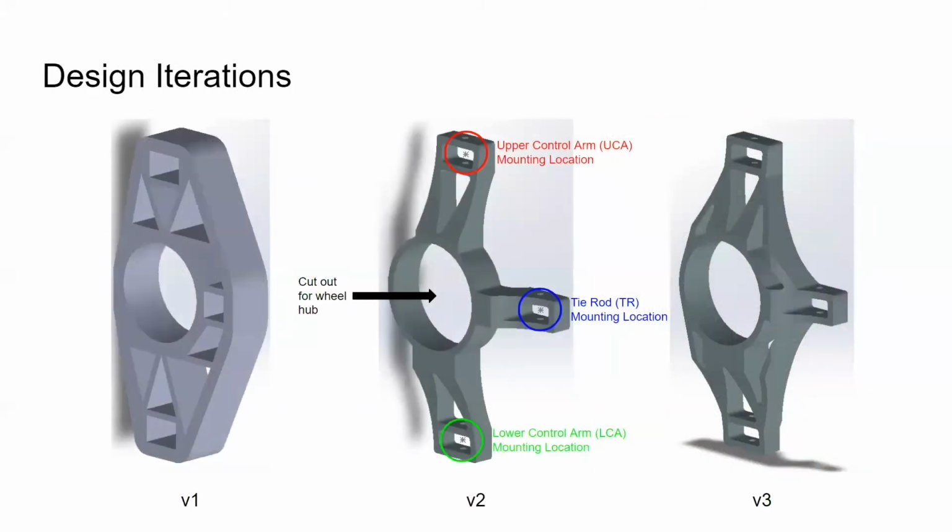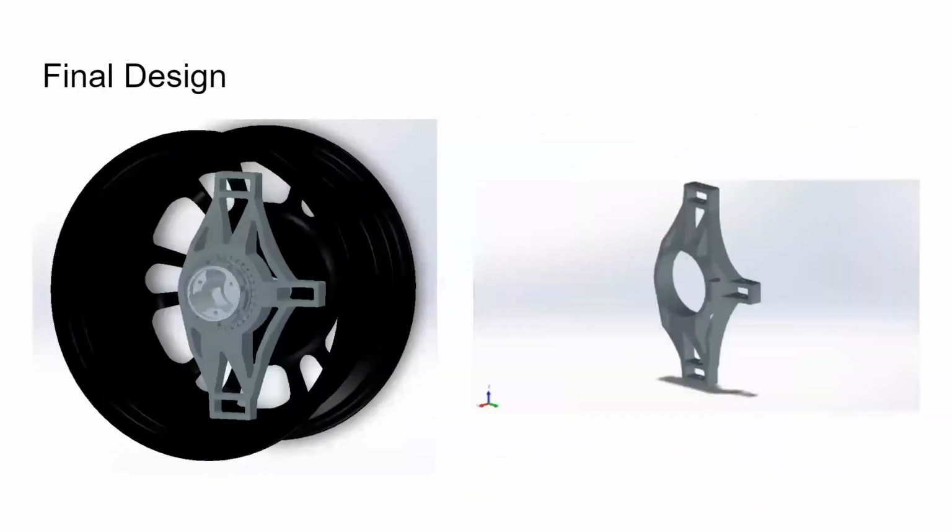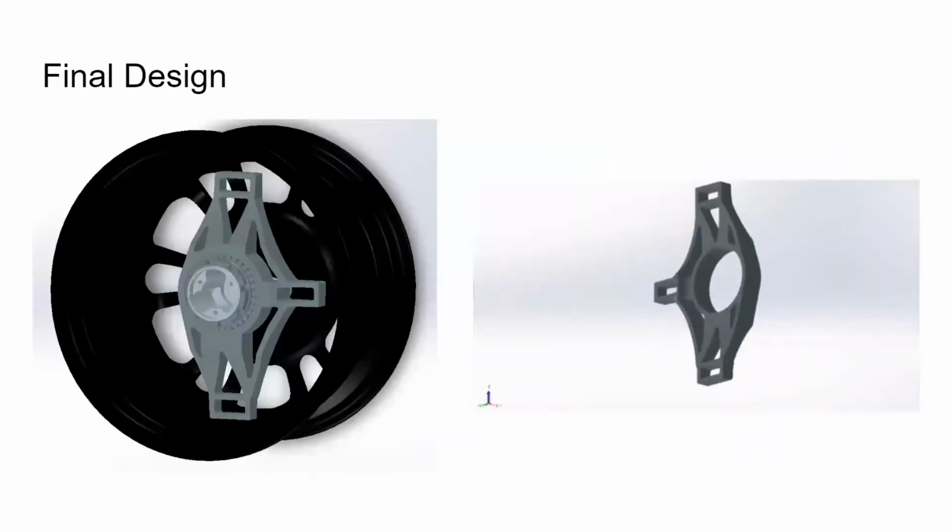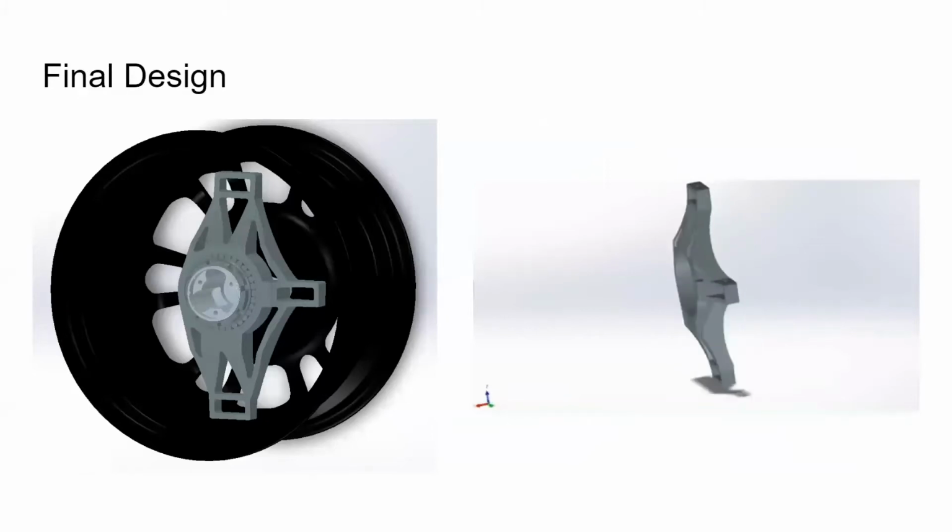The design process for the rear upright yielded 3 iterations. Version 1 is building up the concept from the previous year, while version 2 is a complete redesign with a minimal philosophy. The third and final version merges the best of the two by minimizing the material usage while maintaining the necessary structural rigidity. This upright has been placed into the wheel assembly, seen on the left, and it does not interfere with the rim. This upright improves on each of the 3 identified design improvement areas.